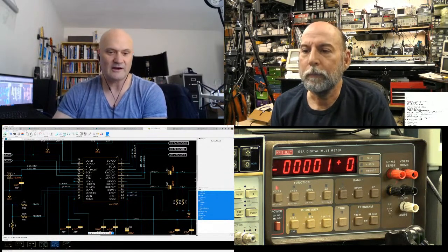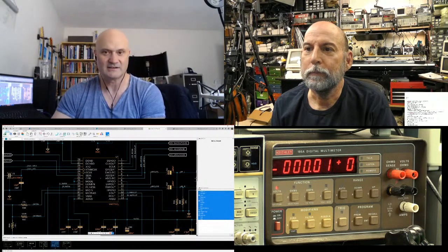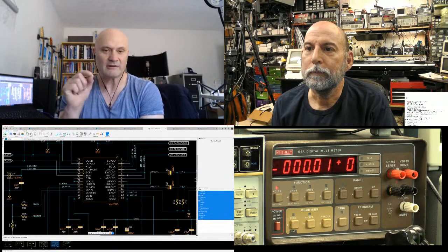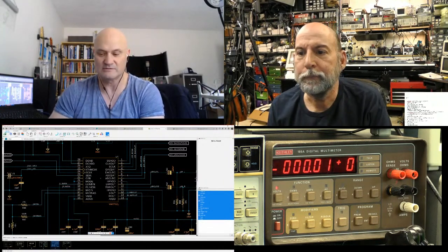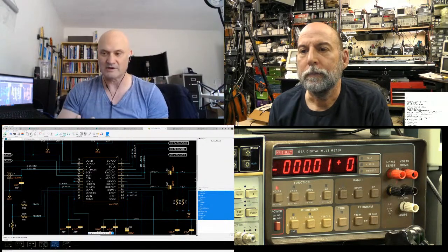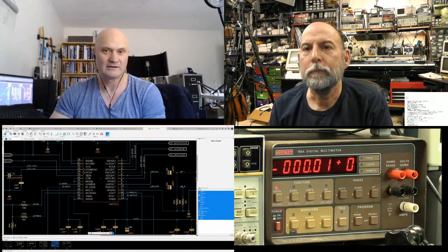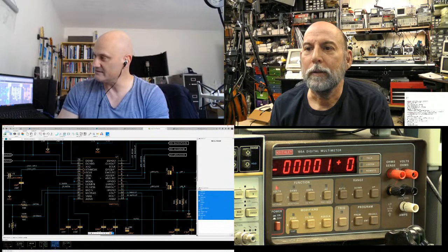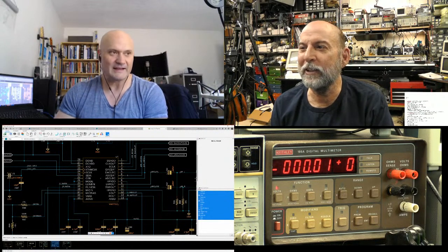And so it's kind of flexible, but it wasn't clear. I read the whole data sheet. It did not say what to do. With most microcontrollers, the I2S interface only has one LR clock pin. It assumes if you're in full duplex mode, you've got the same sample rate for read versus write. And the data sheet didn't say what to do. And I'm like, geez, this is a problem. Do you hook them together or what?